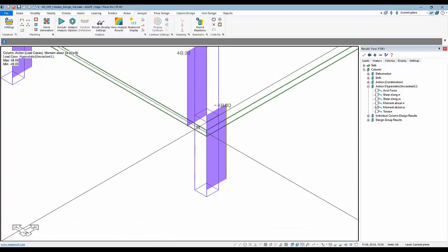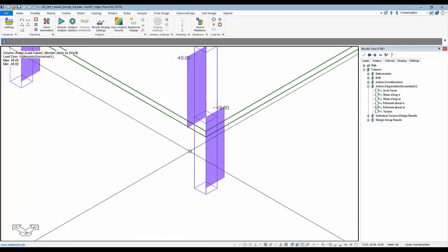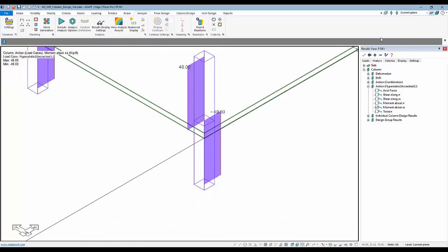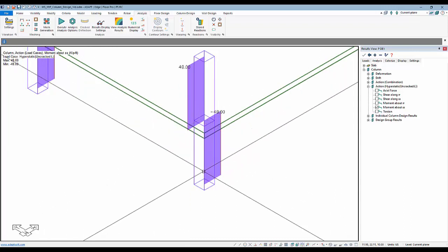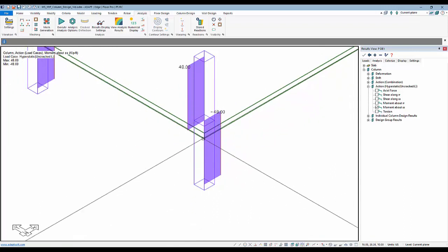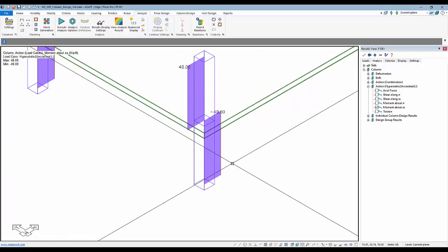Now these are graphical results, so these are truncated back to certain locations. For example, for a strip, you might get column face of support. These are top, bottom, and mid locations for the frame elements that comprise the beams. Those are the forces that we're looking at and the moments.